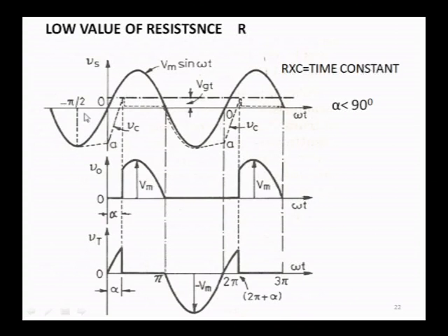You can see this is a negative peak, which is applied across your capacitor. Capacitor charges to this peak value. Then you follow this. This is Vm. This is the input voltage, Vm sin omega t, the input source voltage. So, this is a sine waveform. Now, this Vm is the negative peak here. Now, Vm is decreasing, the input voltage is decreasing and reaching 0.